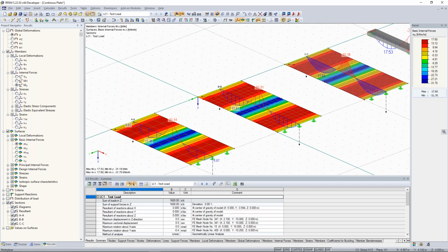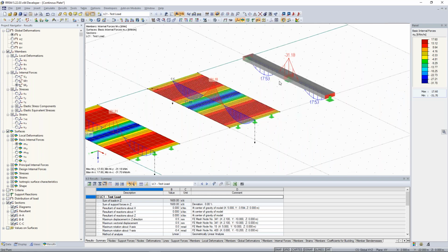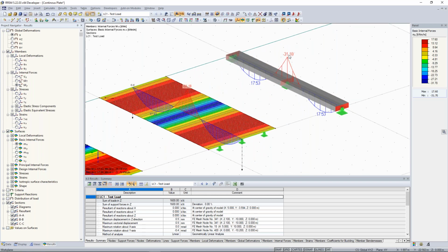And maybe someone of you is asking, okay, why are the internal forces, here in this case, the bending moments, why are they a little bit different in comparison maybe to my hand calculation? Yeah, because in our study, we use our hand calculation. Maybe someone of you is using some formula in order to get that. And normally there should be maybe some nicer values, I would say. Yeah, so not here this 31.80 kilonewton meters, but 38.25 kilonewton meters.